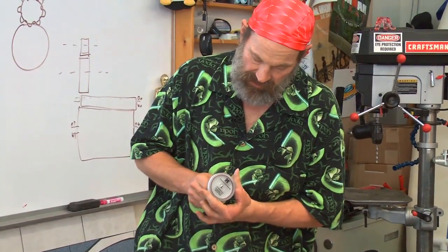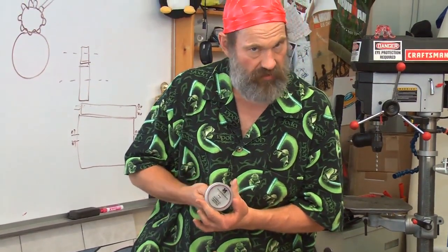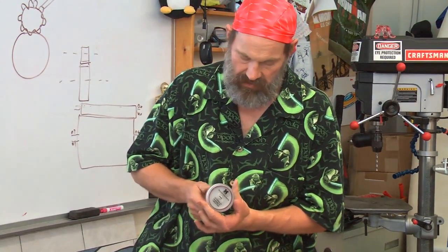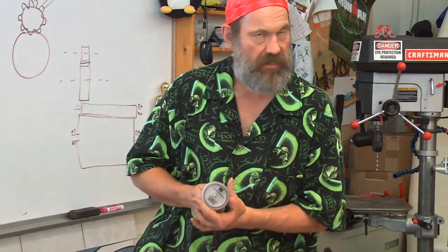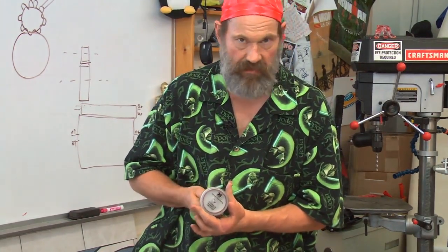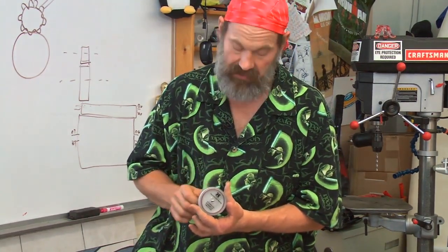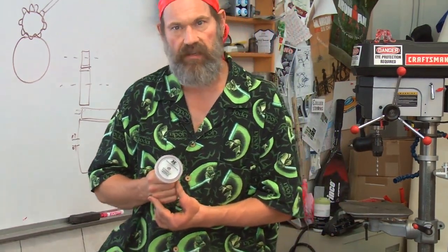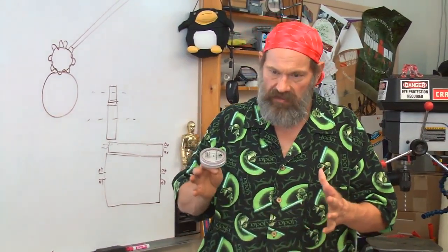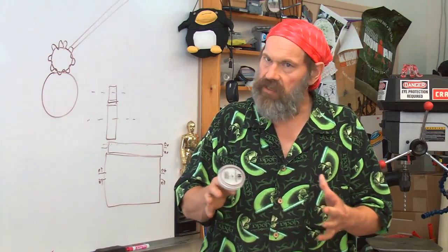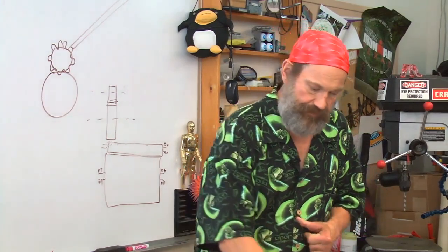The challenge is designing it so that the teeth don't strip off because they are so small, and they have to be small to accommodate that flex spline, and that the flex spline does not fatigue over the lifetime of the gearbox and itself break. And that's the trick in designing these harmonic gear drives. And they can be designed very, very well, with very, very low backlash because they allow that elasticity of the flexural elements to force them together.